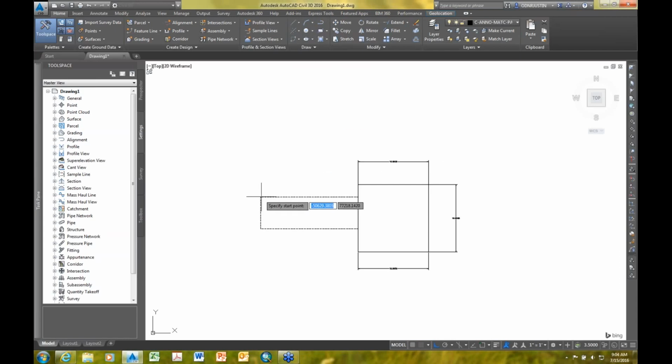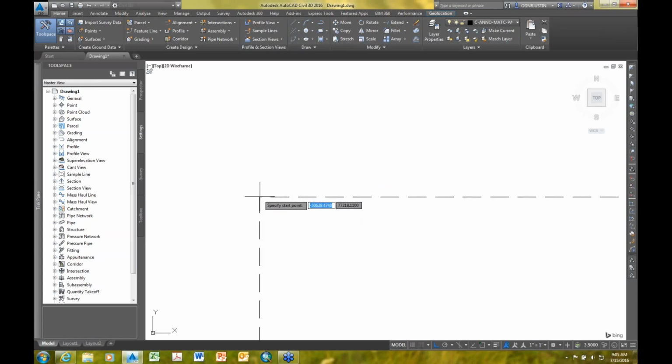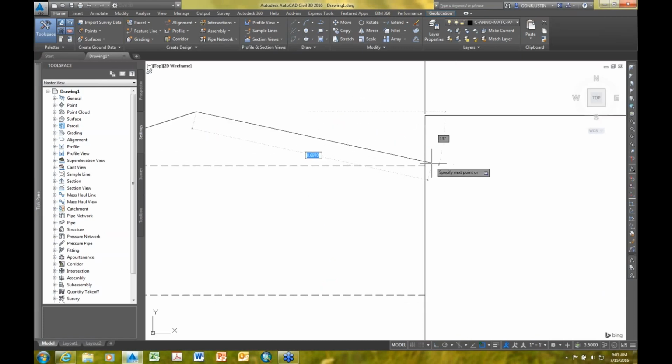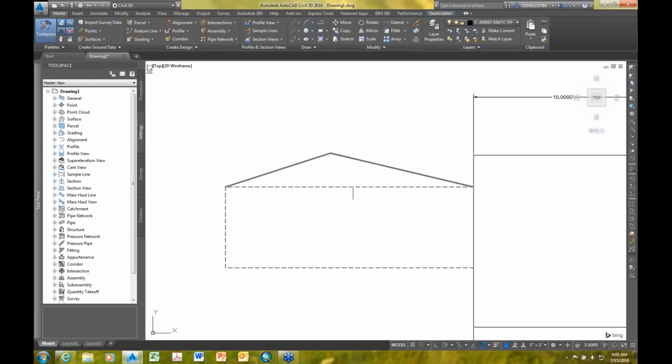If I have a line that's going to continue right off that vertex, I either have to zoom in and guesstimate it, or I can turn my snap on, make sure it's set to endpoint, and you'll see that green box appear knowing I've locked on. I'm in ortho mode, so let's take that off. I've locked on to that corner, and then it'll find maybe my next corner here, and I can click off that. Now I've got a line drawn that snaps to those corners.